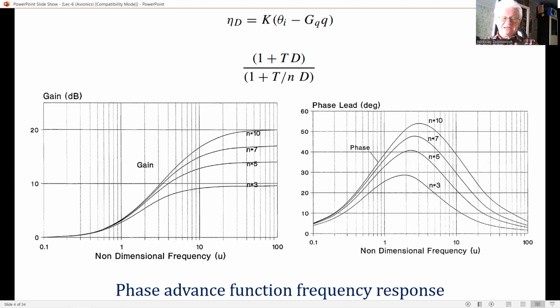This increases the damping of aircraft response and reduces the overshoot to a minimum when responding to an input or disturbance. The control term is filtered to limit the increase in gain at high frequency, and smooths the differentiation process, which amplifies any noise present in the error signal.